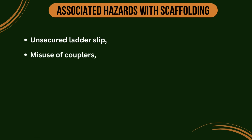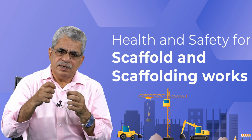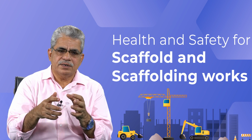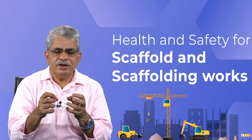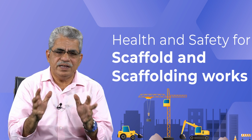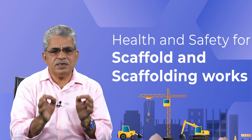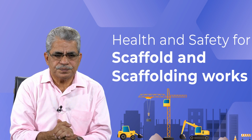Then misuse of couplers. Couplers are used to join two members basically. If we have not properly tightened these couplers, then there may be a failure of the joint which may result in a deadly accident. So we should ensure that couplers are properly used.